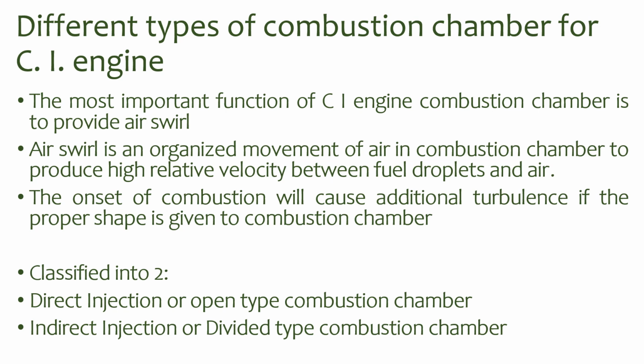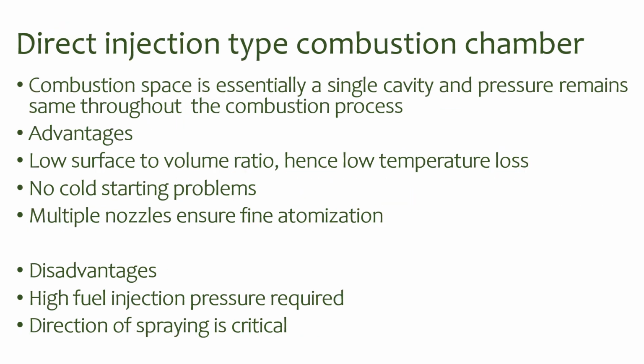This is classified into two: direct injection or open type combustion chamber, and indirect injection or divided type combustion chamber. In the case of a direct injection type combustion chamber, the combustion space is essentially a single cavity and pressure remains the same throughout the combustion process. The advantages are low surface to volume ratio, hence low heat loss, no cold starting problems, and multiple nozzles can ensure fine atomization.